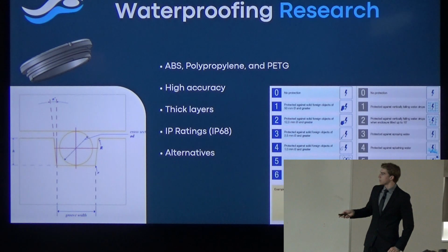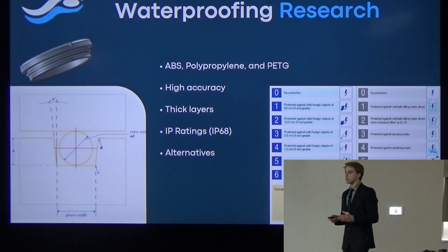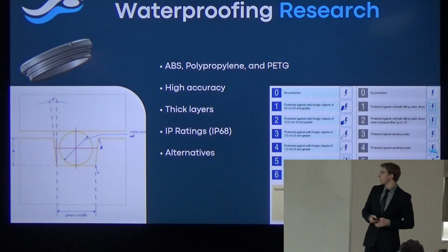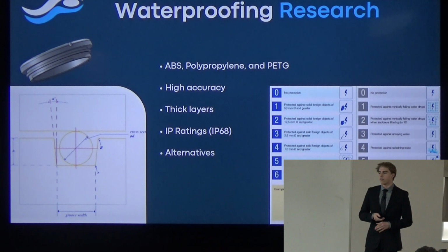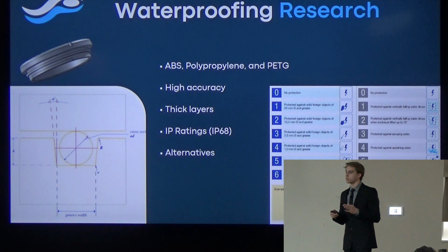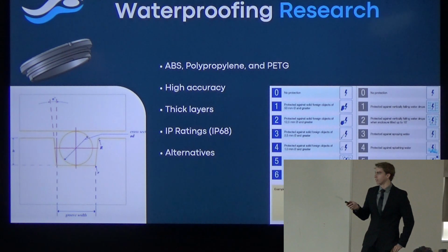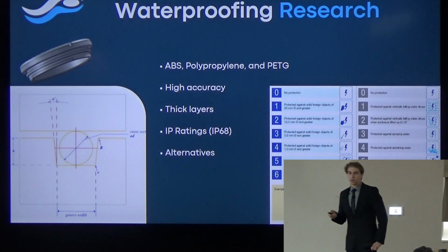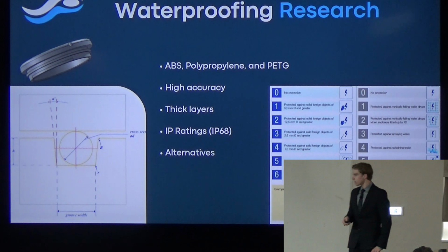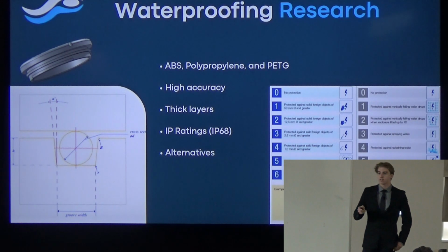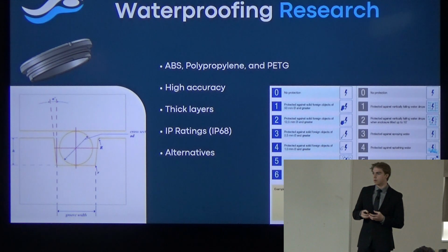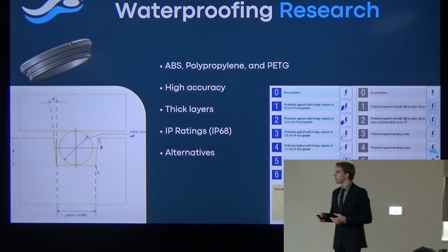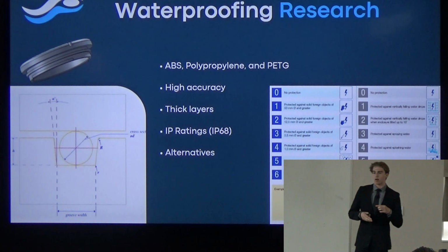I wanted an IP68 rating on my device, which essentially means that the case is dust tight, as well as protected against continuous immersion in water for normal depth and not like scuba diving conditions, which seemed pretty reasonable given my project. Additionally, I looked into alternatives in case the waterproofing didn't work, such as silicone gels to encase the microcontroller, or wax coating on the case to prevent leakage through the O-ring seal.